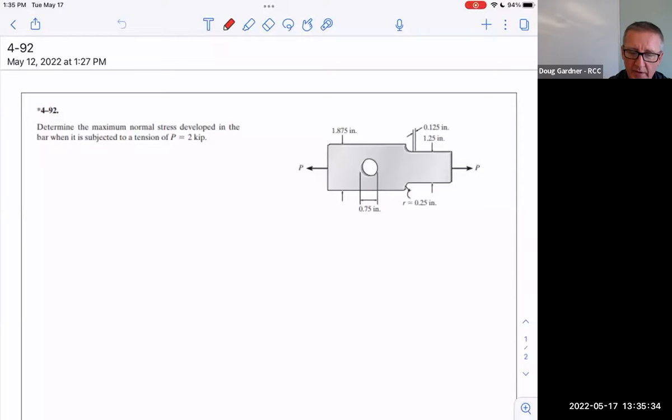It's just saying, what if you knew how much force you're going to put on it? So let's pull 2,000 pounds. If it's the same diameter and everything, wouldn't we just look through the hole? Yeah, now that we just learned that the hole is the weak point, does it make sense we could maybe look at this a little bit differently.